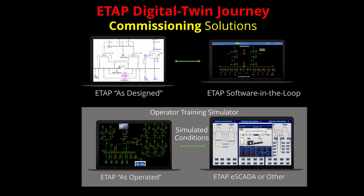So when this model is as designed, it can interface with another ETAP and act as a software in the loop. And this helps you when you don't have a SCADA system. You can validate certain operations with another ETAP design model and see the impact of making certain changes in the system, especially when you're energizing a system piece by piece. In this case, the system is not in normal operation, and it helps you understand the impact when you energize certain large assets within the system before you actually take the action in the system.